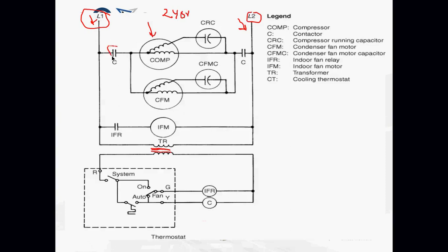But here we have two switching devices. Now, from a personal safety standpoint, what can you tell me about L1 and L2 in terms of safety? Do I need to turn both circuits off in order for the equipment to be safe? Yes. I have two hot legs here. I no longer have a neutral, even though I never trust neutral. So this transformer down here is 240 to my standard of 24.